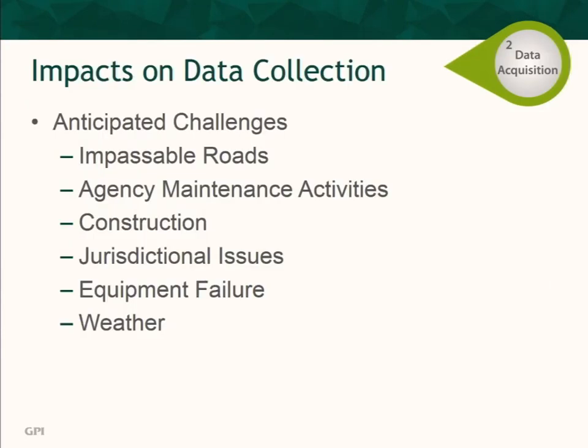The impact is just like driving down the road collecting data. You don't want to drive where you have traffic. We can't. You have to shut down the system if you have traffic. You have to maintain your speed. So you have a driver, a spotter, and a sensor operator. The sensor operator is sitting in the van watching the data coverage, and the spotter is telling the driver, hey, I can see traffic down the road.